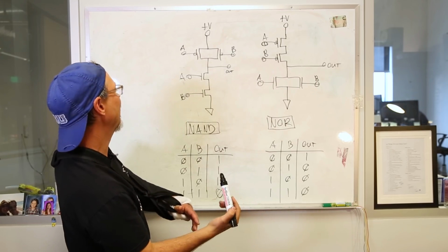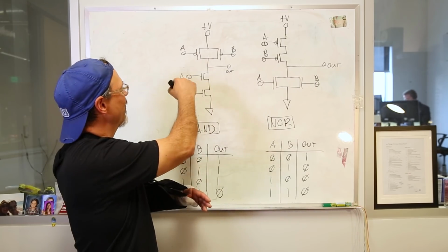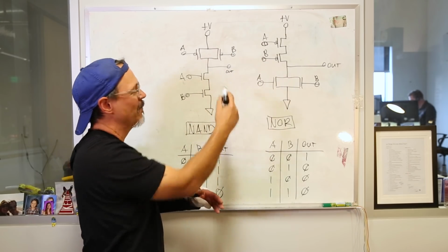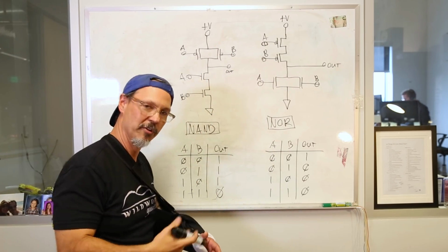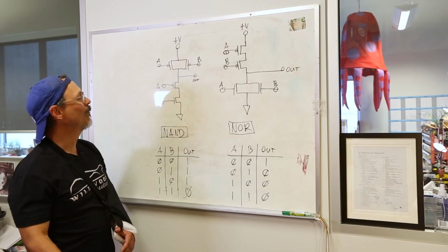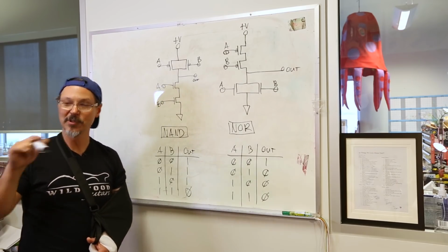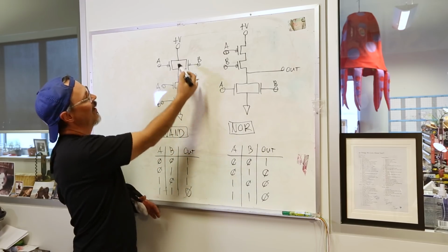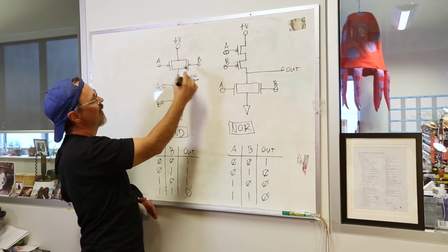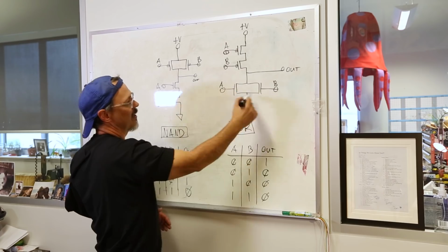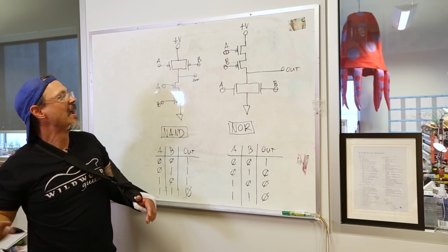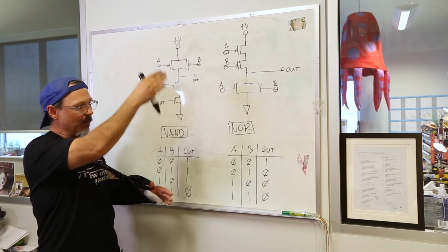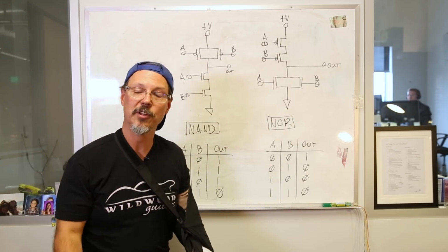And consequently, not only is your input improved, your output impedance is reduced, so it can drive better current. Because the switching time is so short, dramatically shorter in fact, the time where this section and this section, or this section and this section, are on and dumping current from your power supply to ground is much reduced.